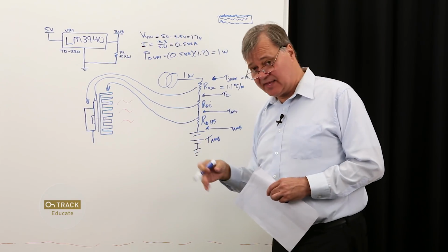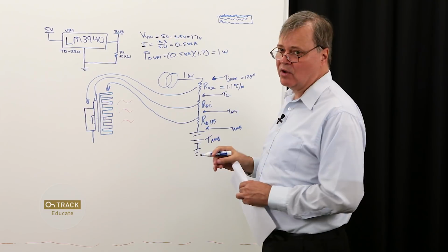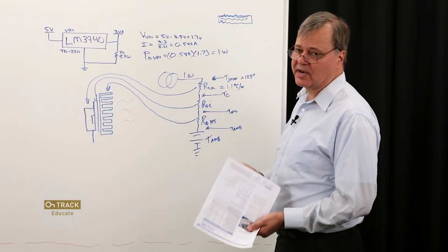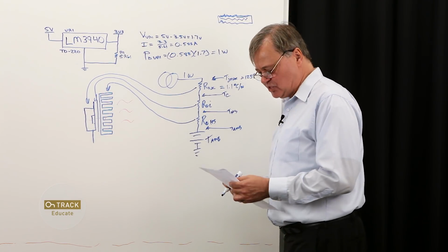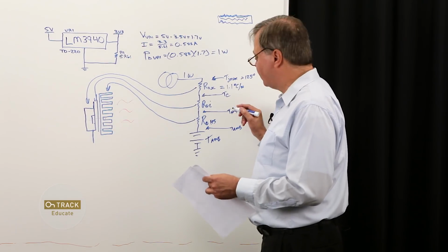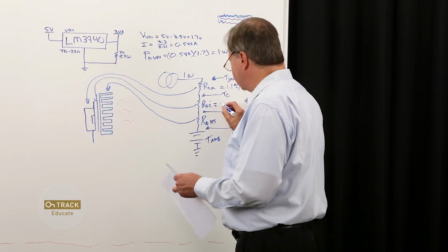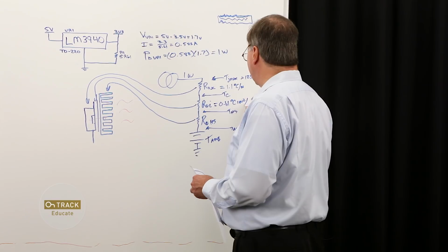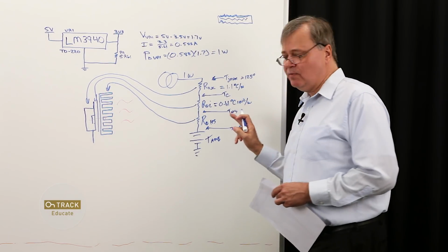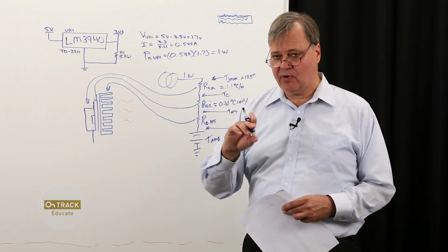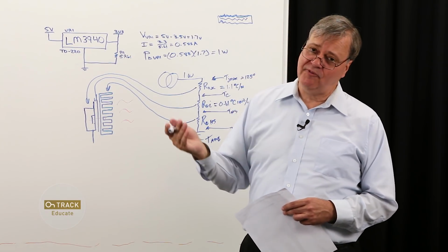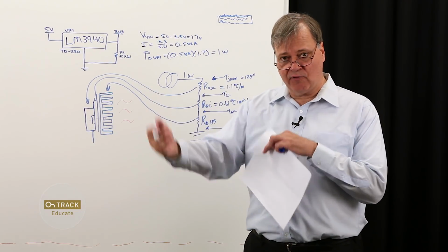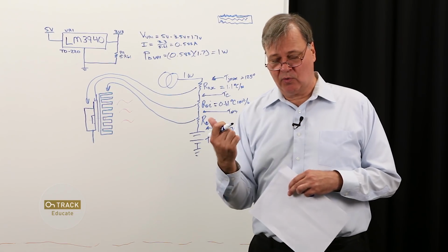If I didn't have that, then I would have to somehow integrate over these two unknown surfaces to figure out what the surface contact is, and that's going to be different for every application. So this brings uniformity to our application. Now, the published value for the thermal resistance of this material is 0.61 degrees C inch squared per watt. This is assuming that the heat is transferring through 1 square inch of area. You remember from the last episode when we started developing our thermal resistance models, we had to consider the area over which our heat flow was being conducted.